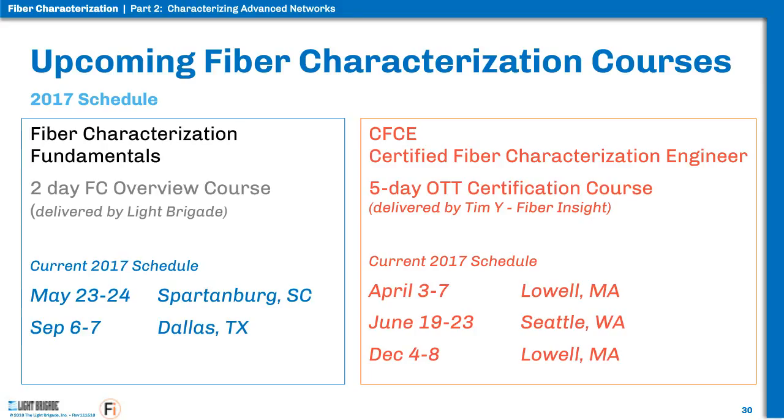Okay, another question is an example, and this is for a 10 gigabit per second route in a metro area using a G.652 fiber for a span of less than 10 miles. Would you expect a failed CD and PMD test? Over 10 miles, no, I wouldn't expect that.